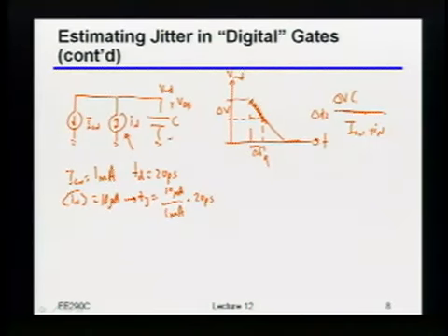So to write that out a little bit more formally, if I looked at the sigma of the timing jitter, but I normalized it to my delay in the first place, that should be equal to the sigma of my current noise divided by my on current. Does that kind of make sense to people?